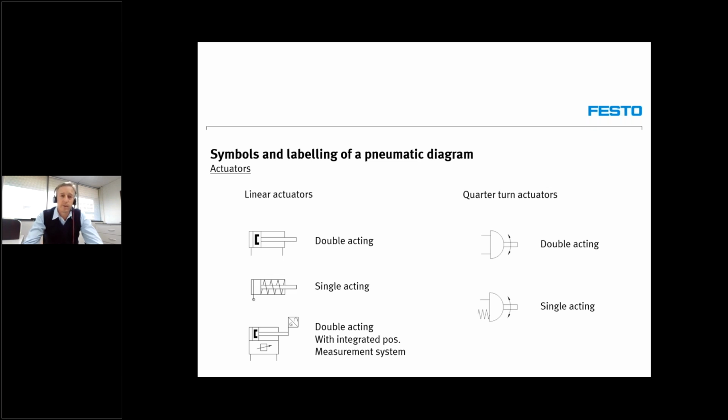if we can move perhaps a valve closer to the actuator, because remember, if you actuate a cylinder, as we saw now, air needs to be exhausted from your actuator through the tubing to your valve. If you move a valve closer to your actuator, then the length of tubing and the amount of air that you need to exhaust is much less. So simple factors like that.